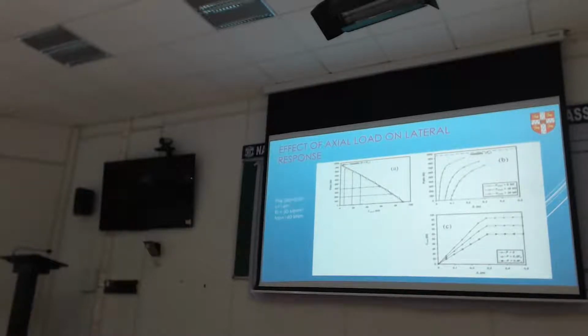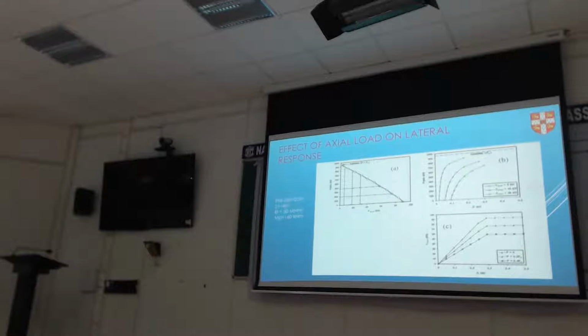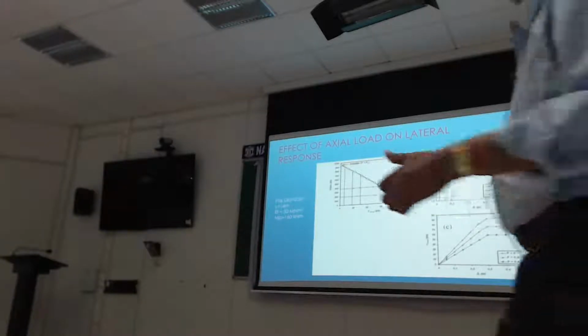And this one is also similar, but getting close to Euler law. For example, if P is zero, axial force is not there, you've got plenty of height on this. Whereas the closer I'm getting, this is 0.2 and 0.4, you see your curves are coming down. So you can make basically design charts like this for a number of pile diameters and so on, which can be used in practice without knowing all the theory, if you like.